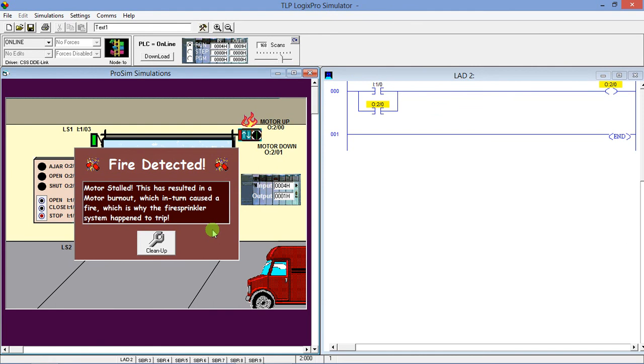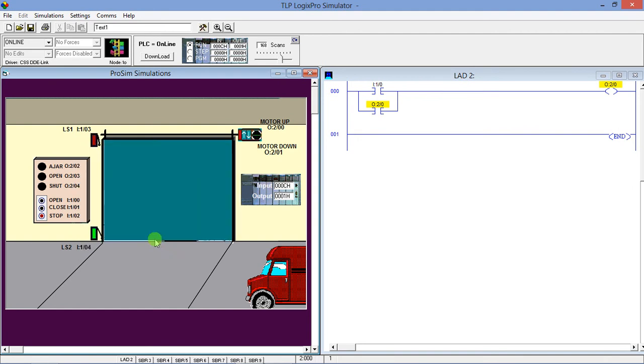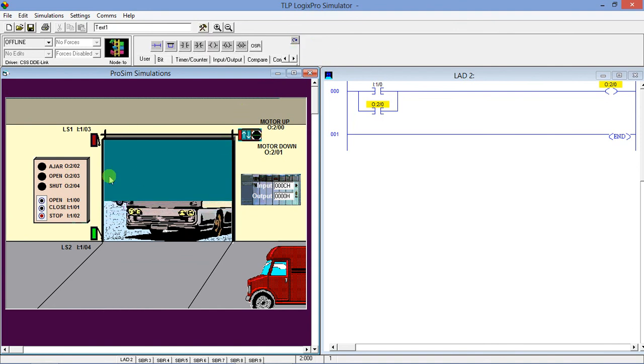The motor will keep running. So here comes the safety function. We are using limit switches for the safety function. Here are two limit switches. Now the limit switch condition is activated. Why? Because the door is here. Where the door is present, the limit switch is activated. If we close the door, the limit switch will be activated. Let's check it out.